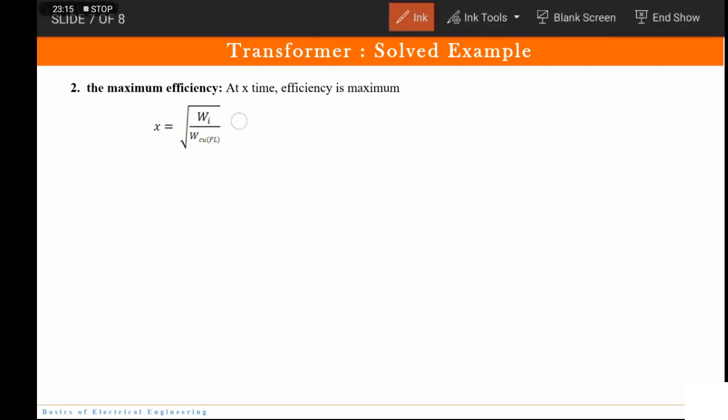Now we have the values, don't we? Yes, we have. So now here you are not going to take 0.450, though the values are going to be the same. See here why we converted it to kilowatt in case of iron loss, core loss, or say copper loss, because one unit was kVA, but here both are same.